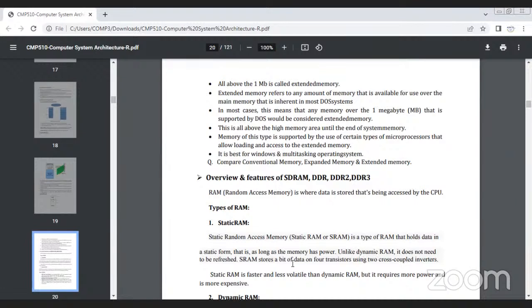The RAM chip's access speed is directly synchronized with the CPU's clock. Okay, in synchronous DRAM, the speed of the RAM chips is directly synchronized with what? The CPU clock. Okay, so the memory chips remain ready for operation when the CPU expects them to be ready. This memory operates at the CPU memory bus without imposing wait states. So this is the synchronous DRAM.